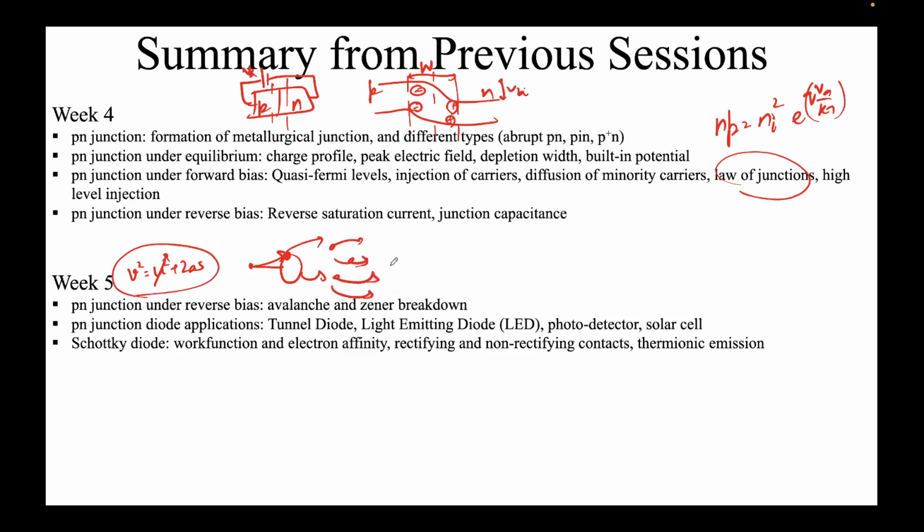In the reverse bias, you do not expect the current to flow, only the reverse saturation current to flow. That is not the case. A large amount of current flows due to the avalanche breakdown. Zener breakdown we saw in case of a heavily doped p-n junction. So in that case, the band diagram looks something like this. P and N side on a reverse junction, because it's rather P plus N plus, and thus you can see that you can have a current flowing, which is typically not the case, like this straddling that can take place.